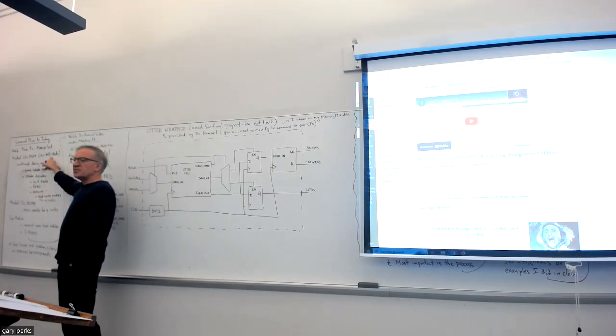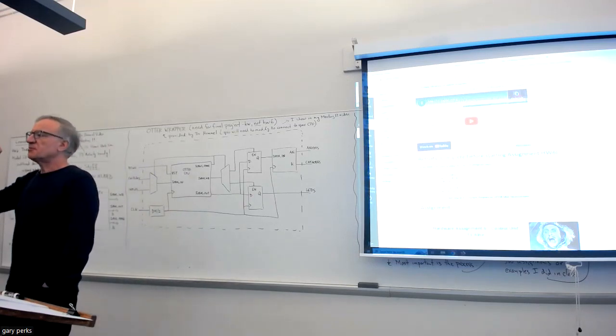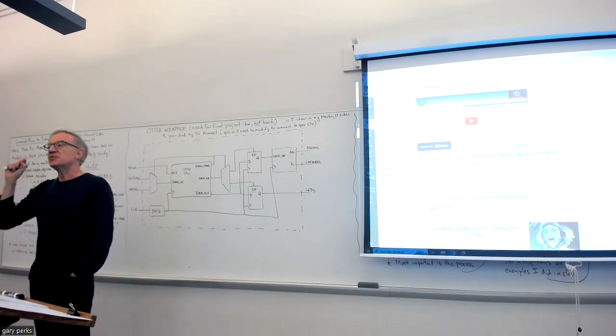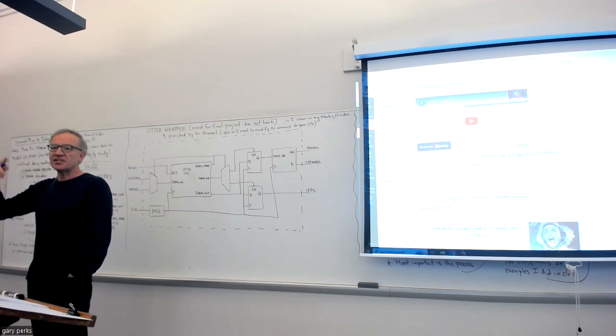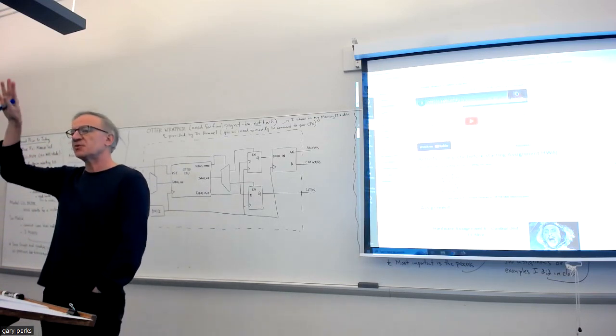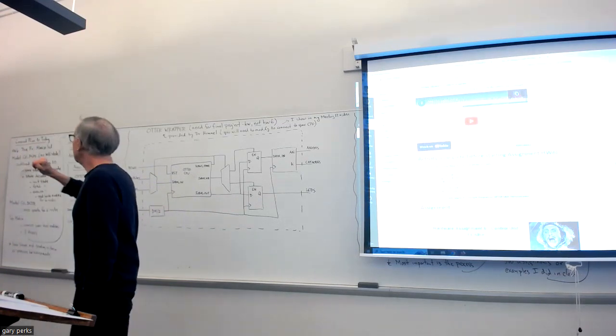Now, we talked about the write back state last class. Remember, the write back state is only necessary for load instructions, like load word, load byte, load half. You don't need a write back state for load upper immediate, LUI, because the data path for that instruction doesn't go through the memory module like the other load instructions do.